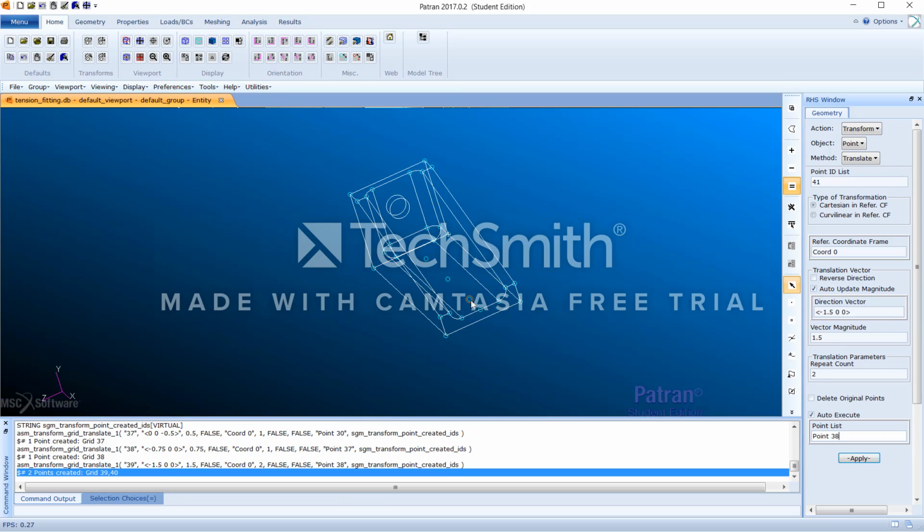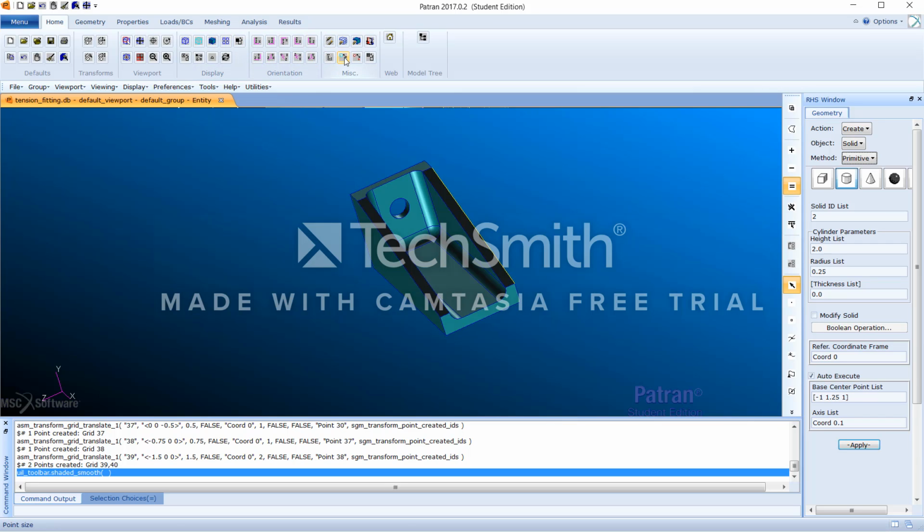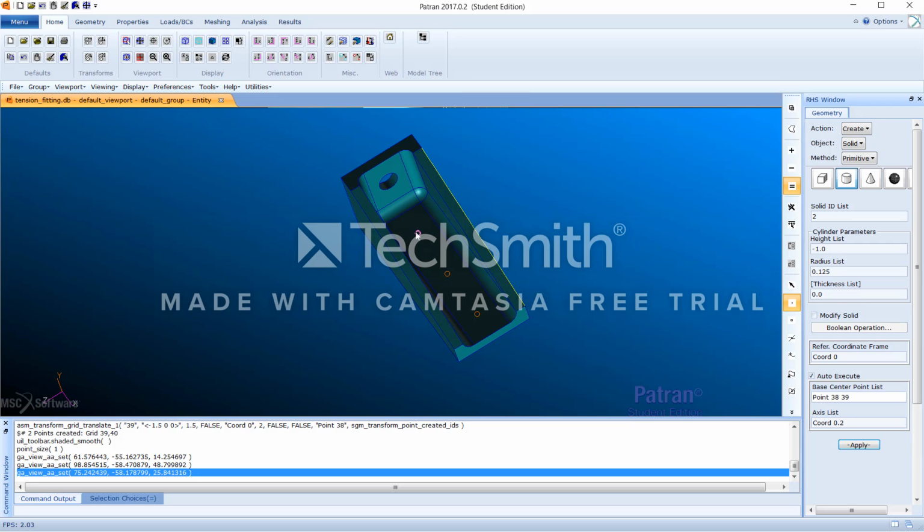Then to create cylinders using points as base centers, and then create holes by subtracting them from the solid. Set action as create, object as solid, and method as primitive. Select the cylinder icon and enter -1 for height and 0.125 for radius, and select the 3 bottom points for base center point list. Enter chord 0.2 for axis list and apply it.